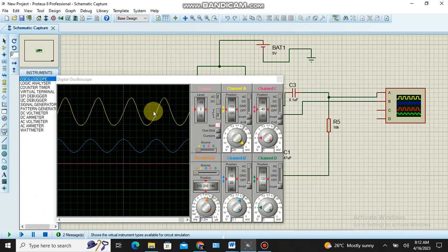See, this is the yellow line. Here on channel A I connected the output signal. So the yellow waveform is the output signal, the blue waveform is the input signal. The signal is amplified. Okay, so this is bigger in size, this is smaller in size. While I zoom this waveform, you can see a little bit of phase difference. There is no exact 180-degree phase shift, but almost some phase difference between input and output. Already I said the exact performance of the amplification happens only in a certain range of frequency.